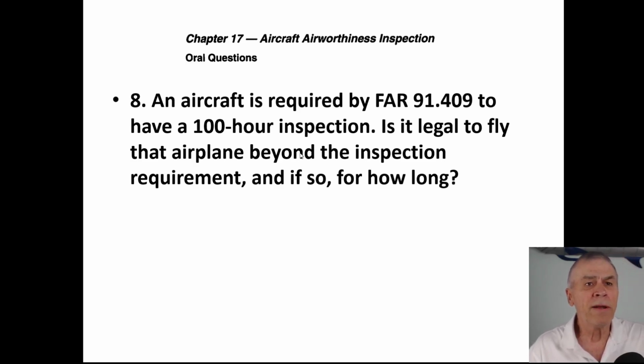Is it legal to fly that airplane beyond the inspection requirement? And if so, for how long? Yes, it is legal in order to have the inspection accomplished. And if so, for how long? That's 10 hours.